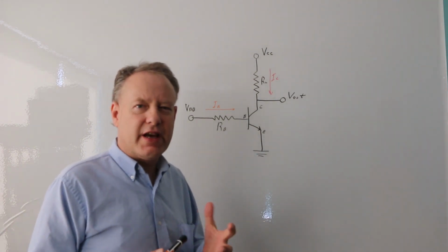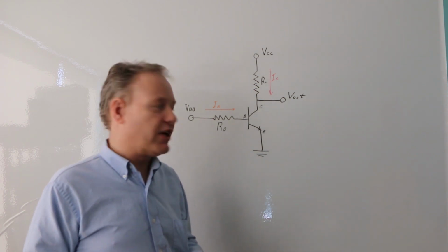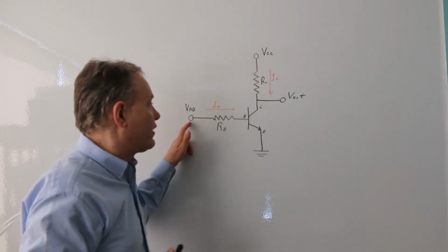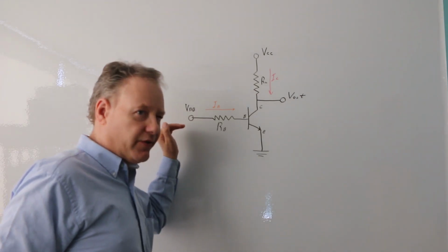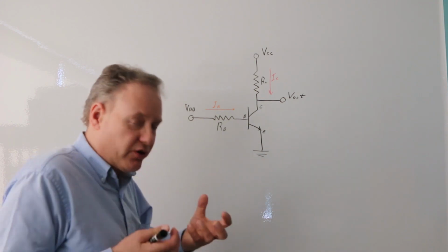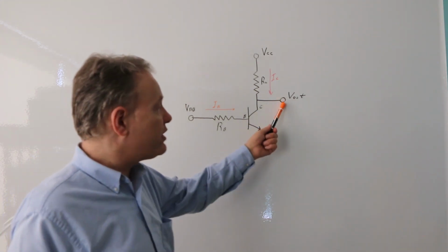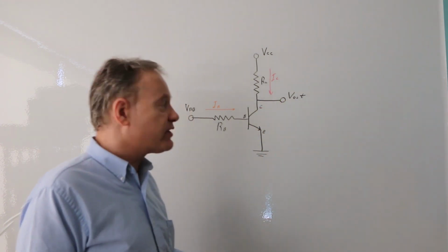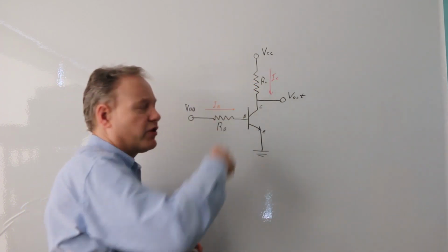One is BJT as an amplifier for voltage. So the voltage amplification is like this. If we were to study what's going out there, depending on what goes in here, we can put a changing voltage in here, which would create a changing current. BJTs are all about seeing how much current's coming in and then putting an output out. That output could be voltage, where we're studying the collector voltage, or we can put the load right there. I could turn that into a motor and control the current going through the motor.